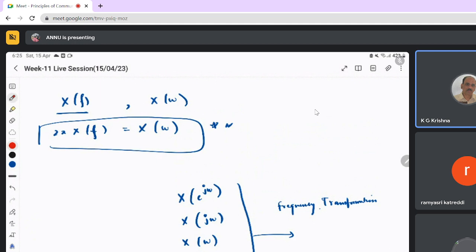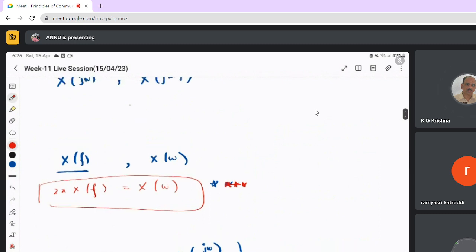Similarly, in the Fourier transform also, if you use the omega notation, then some additional factors of 2 pi will come. In the sinc formulations, you also get confused. For example, the integral from minus tau by 2 to tau by 2 of A gives A tau sinc f tau. I will definitely suggest you go with f. Whenever f is there, you multiply by 2 pi, then you don't have any issue. So A tau sinc f tau is the formulation.